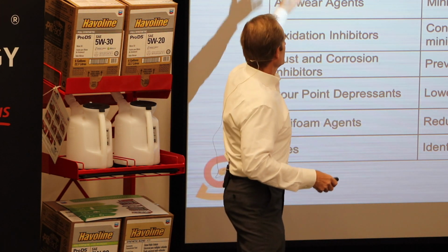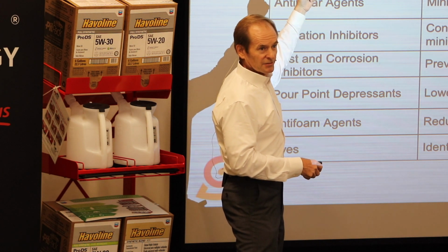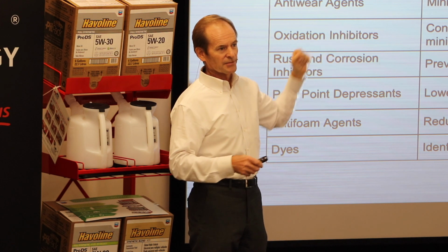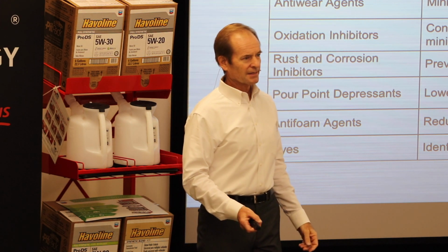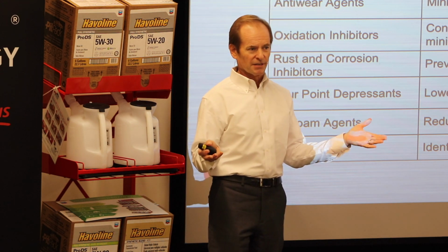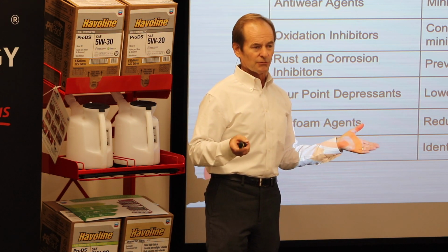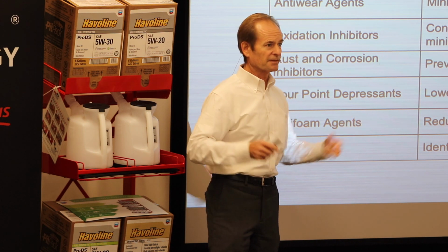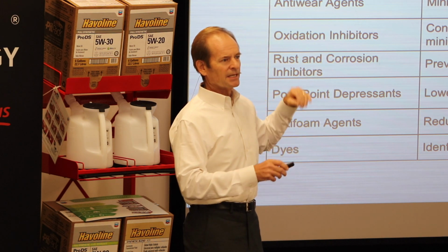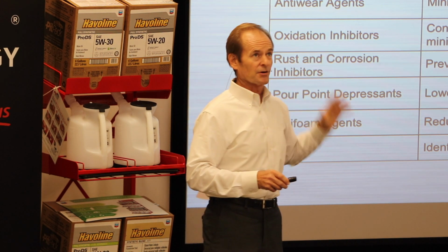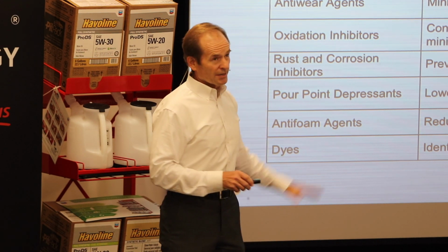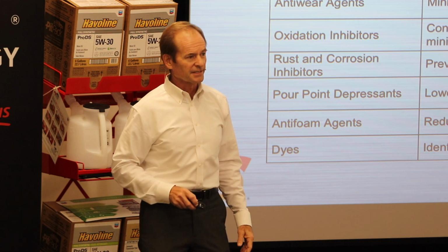Some of them are just dirt cheap compared to the others. You can find viscosity index improvers that are really great and some that are really, really cheap. In the world of additives, viscosity index improvers, the stuff that gives you multi-grade, are a good example of get what you pay for on the formulation side. So these are some of the things that make a difference in the different oils available in the market. All right, and that's all I'm going to hammer on the additive side of things here.